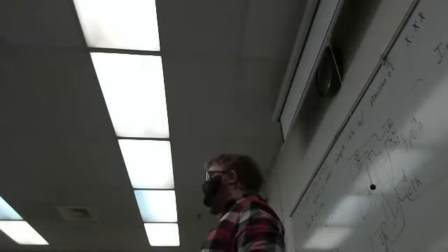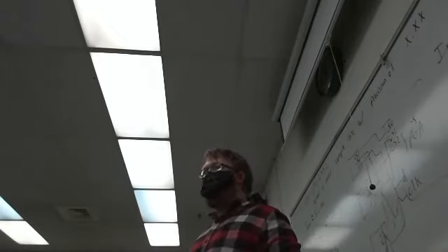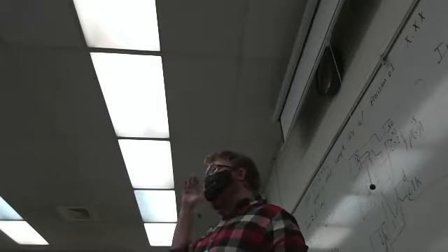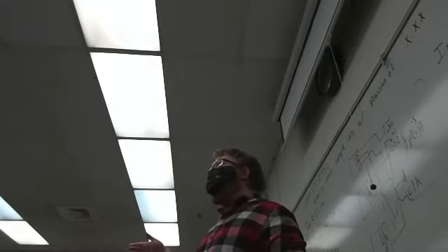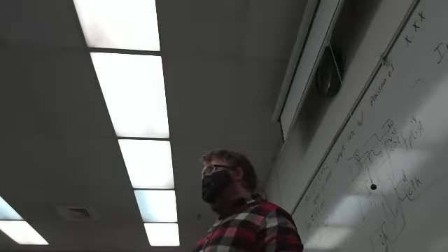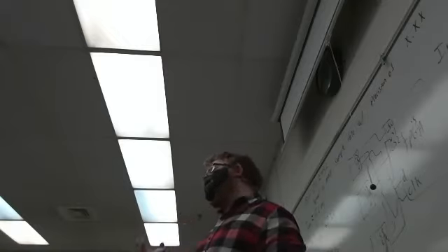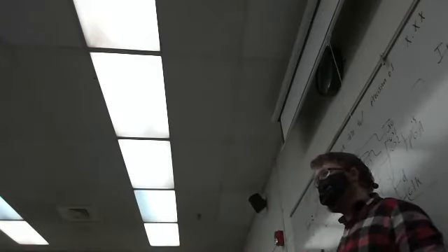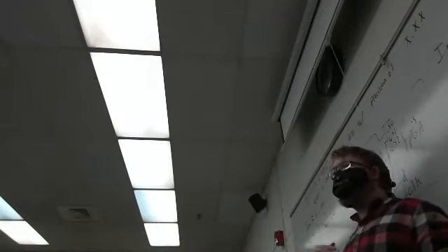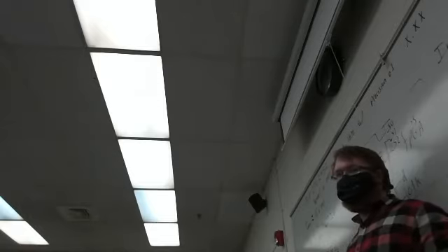Wait, what? So you can just pull it high and then just keep reading? No, if you pull it high, it will do another conversion. And then to read that conversion, you drop chip select back low again. Or you can go into continuous read mode and just keep providing it with the clock while holding chip select low. So there's two ways in this one to tell it to do another conversion.